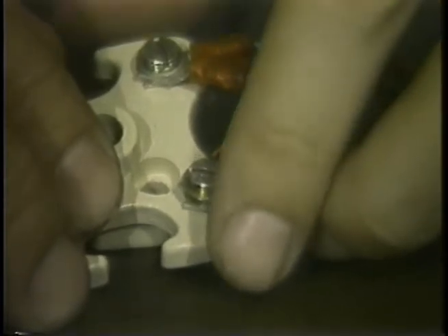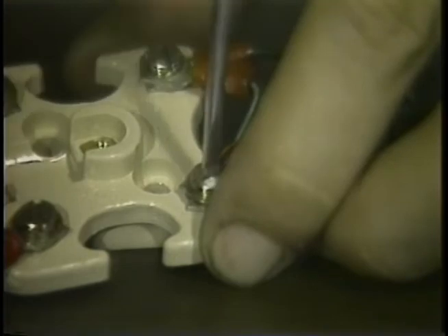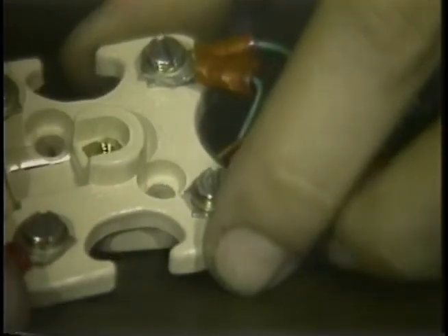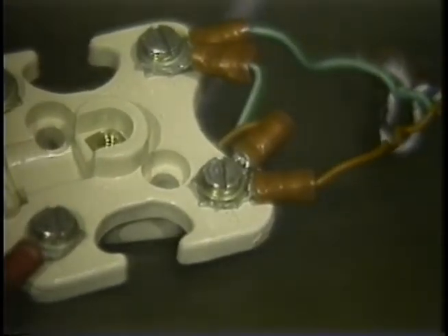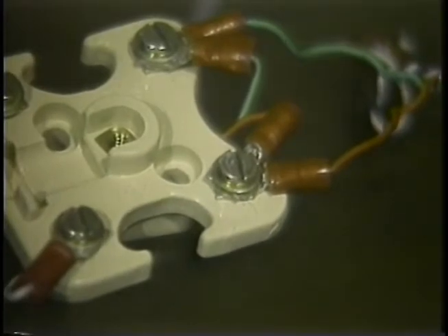Controlled carrier is required for the remote modems for multi-drop lines because they all join their transmit lines together. The central site master modem can't listen to all remote stations at once, just to one remote modem at a time.